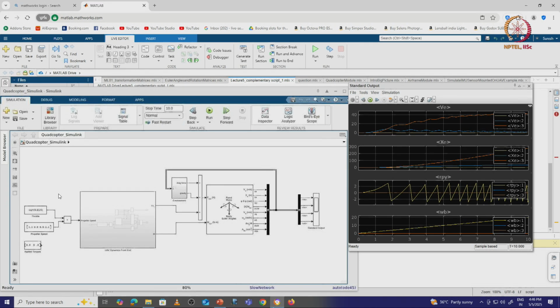I can compute Ix, Iy, Iz, including the structure mass distributions. You can just add that information. You can look at the landing gear, its position and mass, compute Ix, Iy, Iz, and substitute them here. You can do a bench test to get thrust. You can take a single motor propeller system, get the relationship between RPM and torque, and update it. If you have the particular motor constants, you can update them so that you can emulate this response.